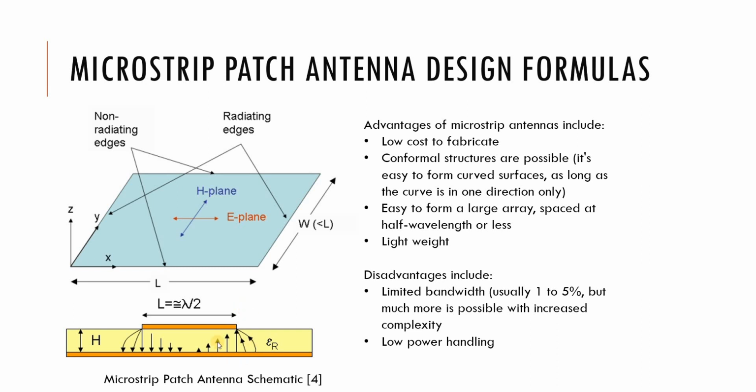And you can see the electric field distribution of the antenna. As you know, the patch antenna can be assumed as an open circuit transmission line. Voltage reflection coefficient will be 1 at the end of the antenna at the open port, and voltage and current are out of phase.